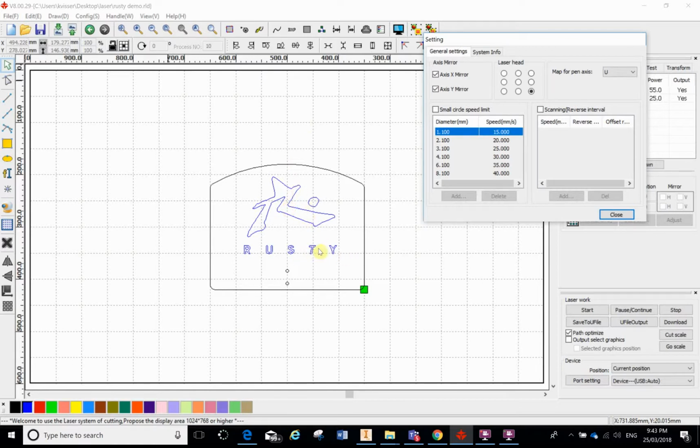And what that means is that if there is any bleeding or staining from the smoke and residue coming off the product, when we keep lasering, it's going to laser over the top of that, as opposed to starting here and the machine working its way down like my cursor is doing at the moment, and smoke and resin and all the residue stuff pouring back over our finished cut.